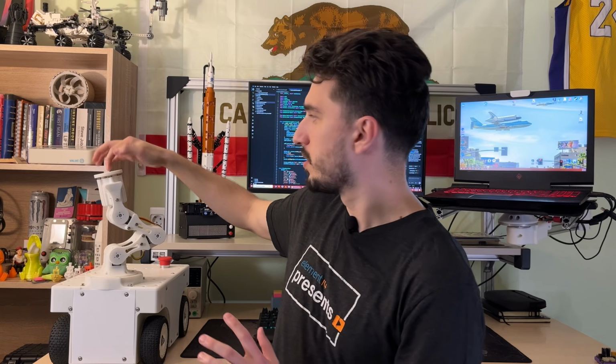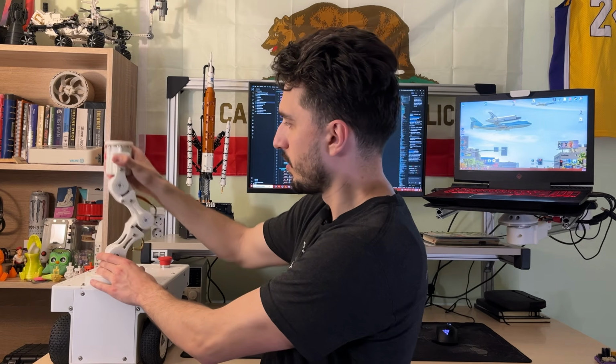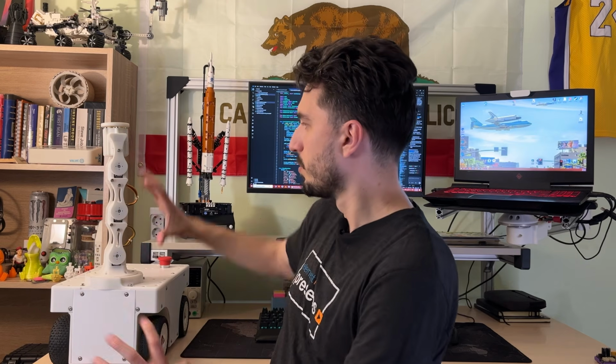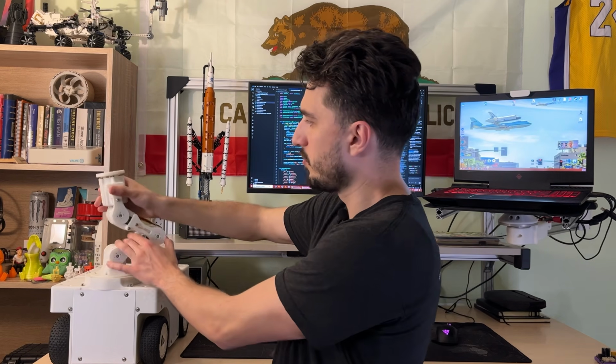Just imagine if we want this tip to move straight up, it would need to go somewhere like this, and you see how all of the motors moved in unison. Now for the arm to get from this position to this position, we have also done this. And maybe it would have done that if we just gave it random references, but if we tune everything nicely, we can get those smooth movements and control it in space and also time. So yeah, that's all of the things that we will need for now for low-level control.